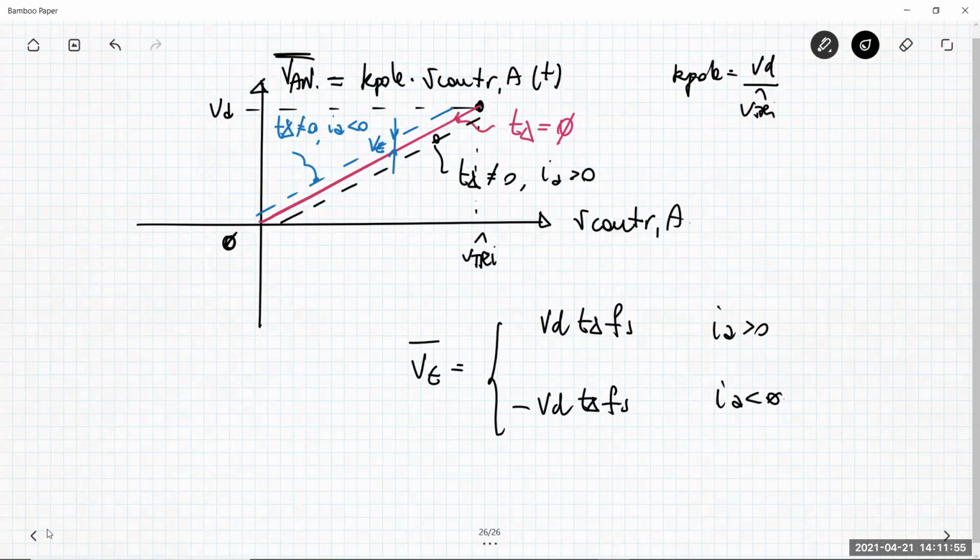But this value can be corrected by the negative feedback, so there is no huge problem in a DC-DC converter. Basically the feedback can recognize the difference in the average value, and basically in the current flowing into the motor, and then correct the duty cycle in order to get the same value you want as a target. So this error can be somewhere compensated.